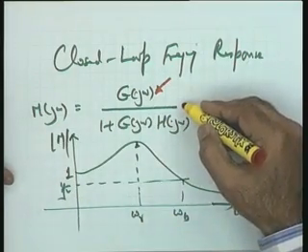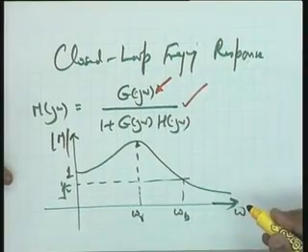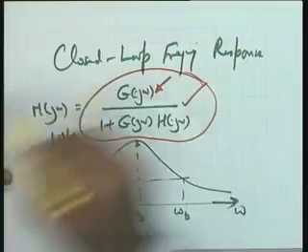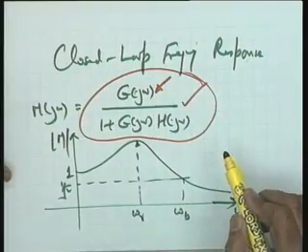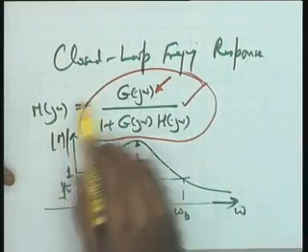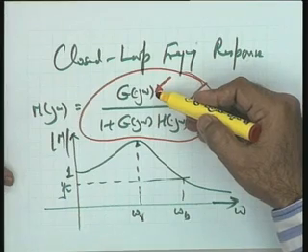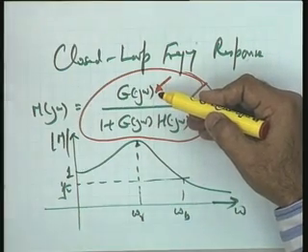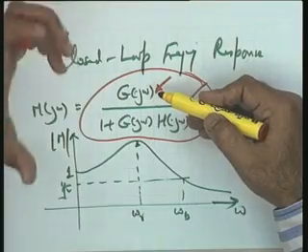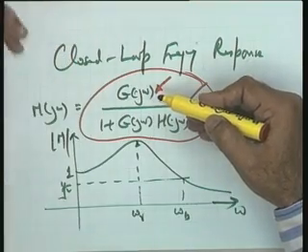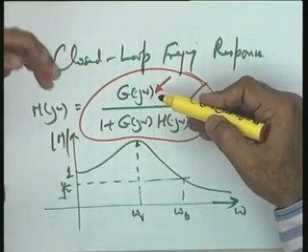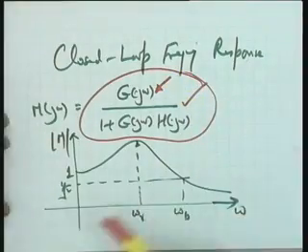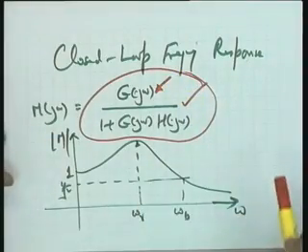But analytically, without the use of a computer, with paper and pencil design, it really becomes very difficult to get the closed loop response given open loop frequency response data. So some sort of graphical methods, some simple techniques, are required, and those techniques have been developed. Using them, we should be able to get the values of Mr, omega r and omega b.